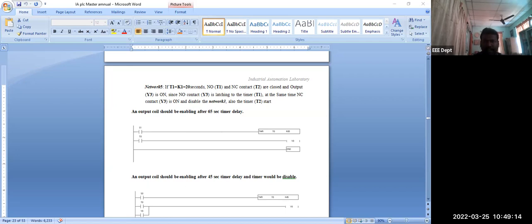So after this, the ladder diagram is drawn. After that, compile the system. After compiling, the end bar will appear like this. Then we have to simulate the system once again, and click to download the current open program to the PLC. After that you have to click the run button. Do you wish to continue? Yes.